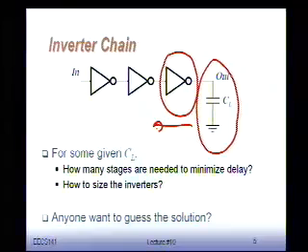So the next gate is going to be loaded, and so on and so forth. So you have to optimize the whole chain in one shot. Somewhere here we start with a tiny capacitor, which is your internal capacitance, let's say, in an ALU or a multiplier or an adder. Let's say of the range of a couple of femtofarads, typically. In 90 nanometer technology, internal nodes have about a femtofarad capacitance. And then you have to drive this big capacitor, which could be hundreds of femtofarads, could be a picofarad. And I want to do this fast.